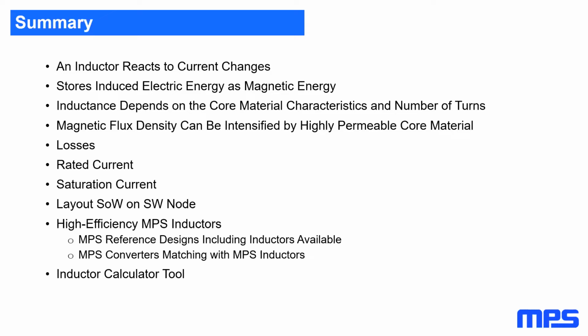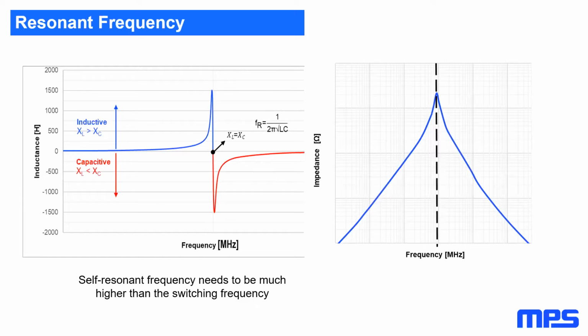All right. And then how is inductor parasitic capacitance controlled? It's not really controlled. Of course, we are trying to have very tight windings of the inductor, because we don't want a higher resistance. So we need to reduce the resistance, and you can reach this by having an efficient winding of the core. But we don't have any measurement or control in production regarding the capacitance between the windings.